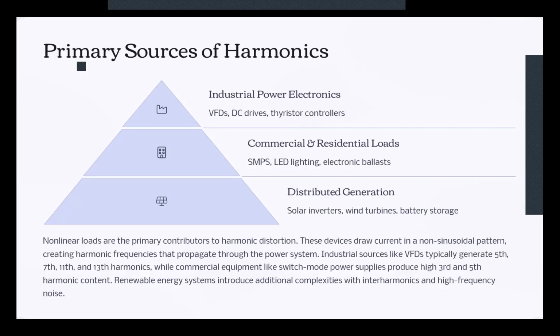And besides that, nonlinear loads are also one of the primary contributors to harmonic distortion because they draw current unevenly, and the current that they draw doesn't follow a pure sinusoidal wave. So they don't have symmetry, they have a distortion on that sinusoidal wave.